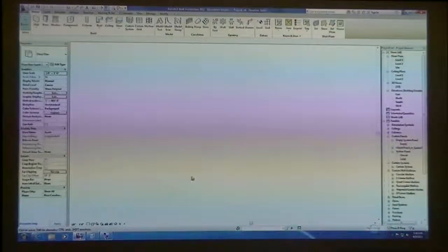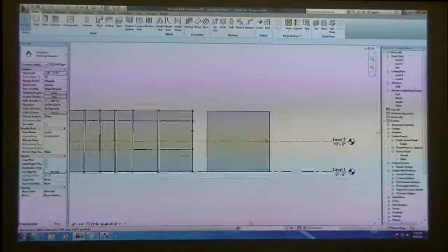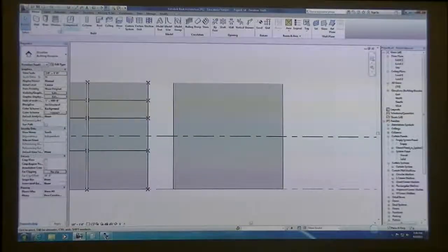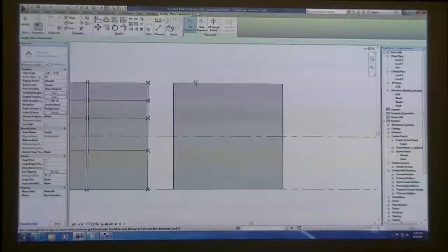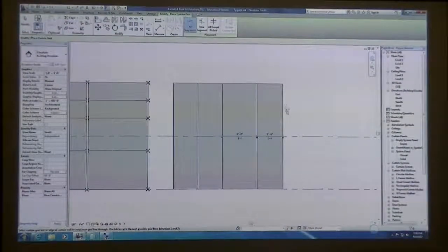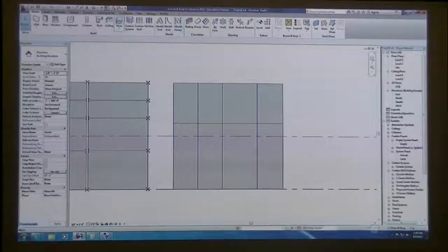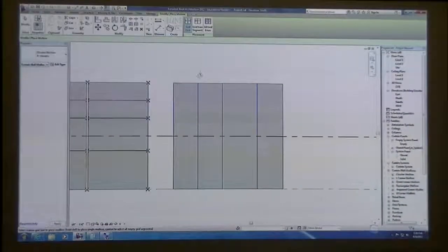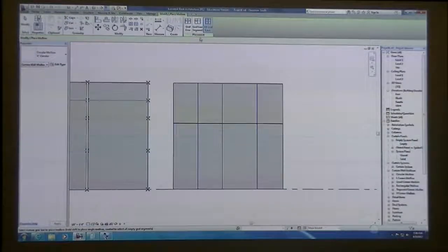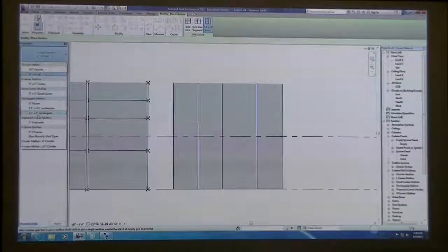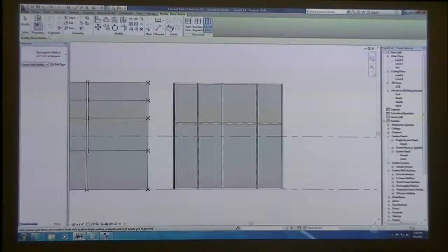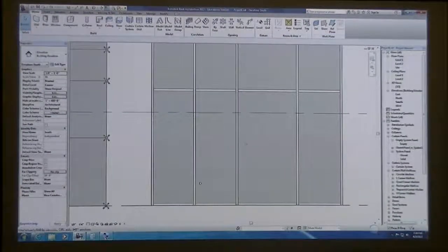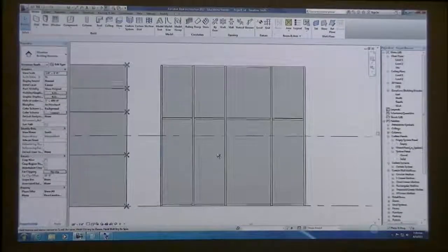And if I look at that in elevation, I've got my other sheet of glass to the side. Again, under Home, and then divide this up into some grid pieces. And this time I'm just going to apply mullions to all the grid segments. And for right now, I'll just make this our 2.5 inch by 5 inch rectangular mullions. Now let's say I wanted to place a door into this piece of glass at this location.